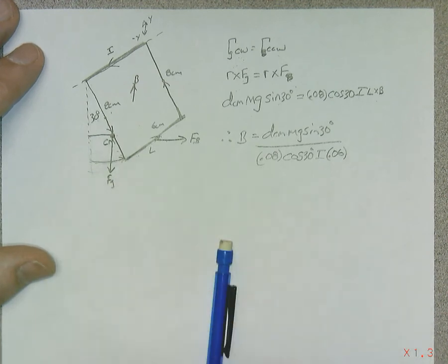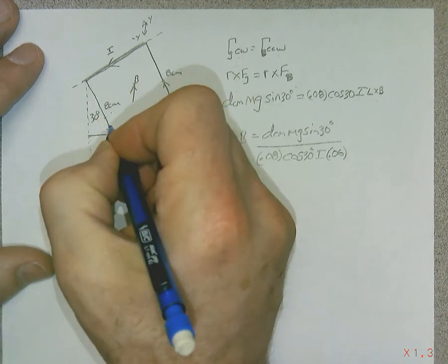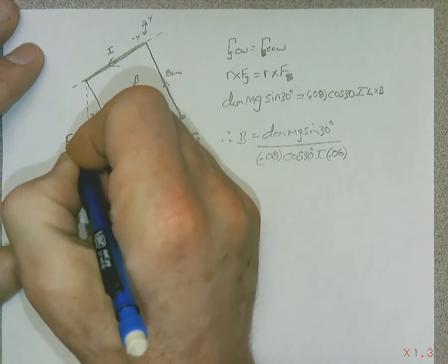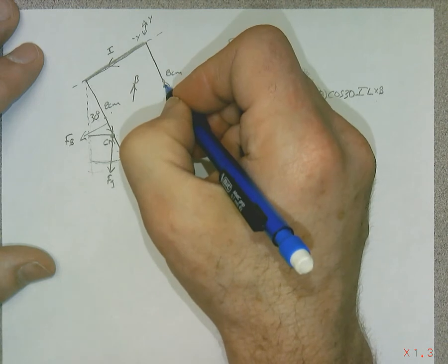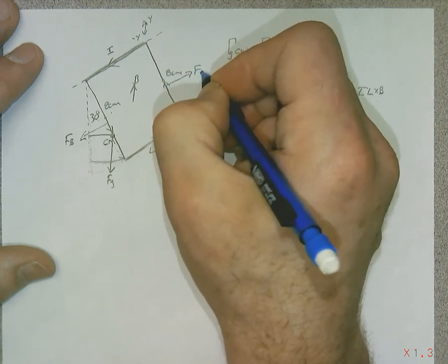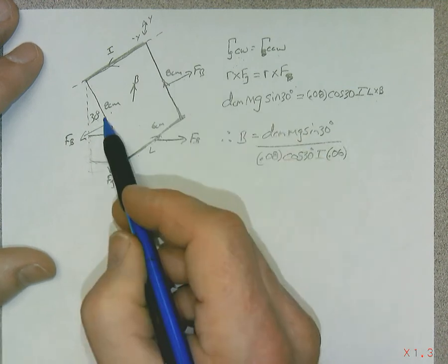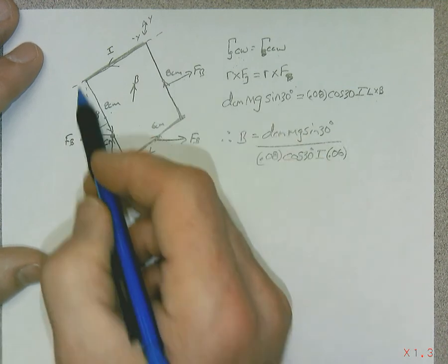And then with your fingers up, you'll see the palm is pointing, which causes a force outward like this. So there's a magnetic force outward here, and for the considerations over here, there's a magnetic force like this. But that doesn't produce any torque. That tries to stretch the wire out this way and this way. It does not produce any torque.